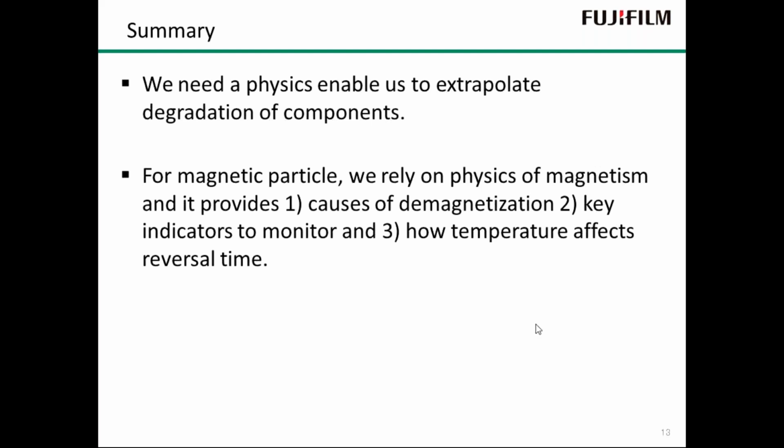It may be true that if you tested at 160 C instead of at 90 F, you could accelerate that and correlate those two things together. But it may also be true that the rubbers in the tire do not act linearly and are not projectable between those two operating points.